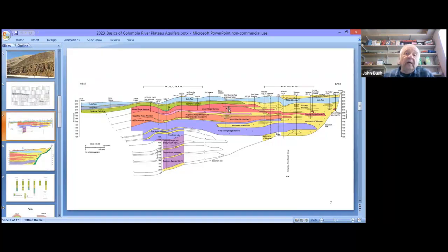And when you examine numerous wells, I was trying to think how many, all of a sudden I can't remember, but I know we've examined over 20 wells in the central part of the basin where we don't have any deep wells with the exception of the test well. Between here and the Butte Gap well, we now have a lot of wells that have gone down 500 or 600 feet and are crossing 2 or 3, maybe even 4 intraflow contacts.